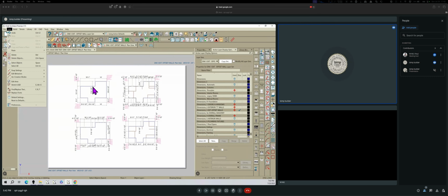I'm just trying to see what kind of roof design options I can come up with, because I change plate heights and roof pitches. Now this is a small house compared to my big estate homes and complex roofs, but it works on the same principle. I block out that roof, and that way I have a sense of what I can do with the elevation.